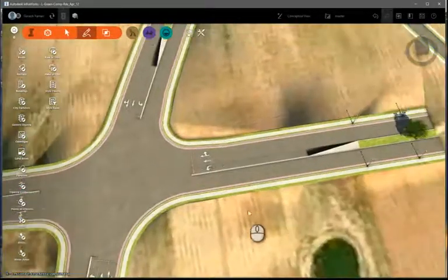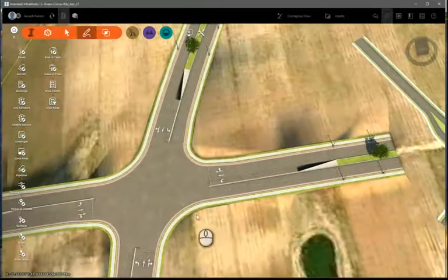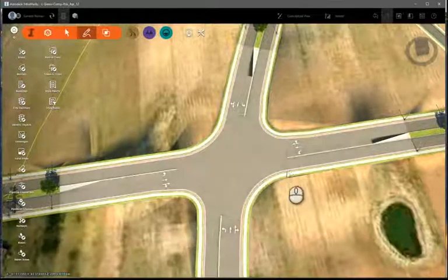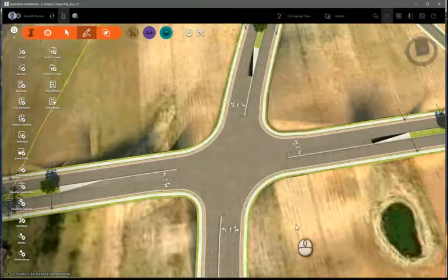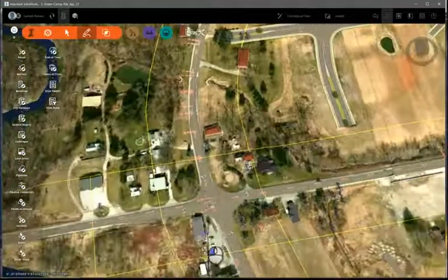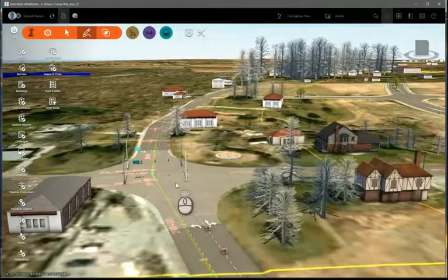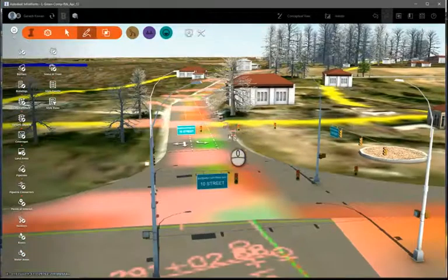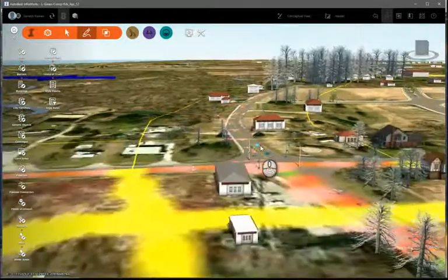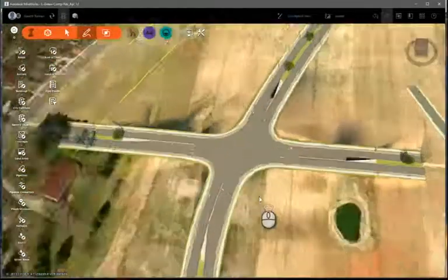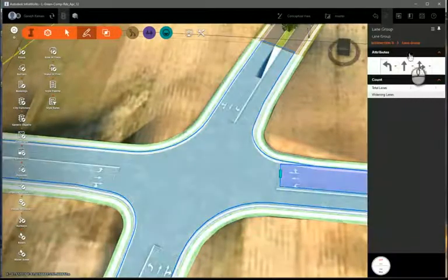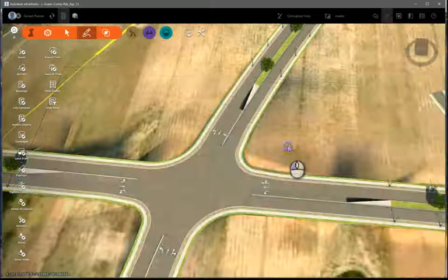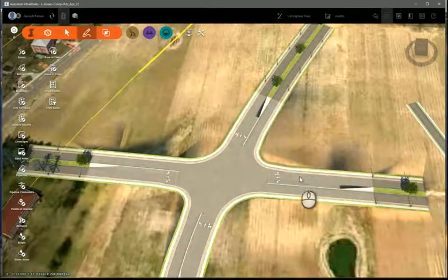Now, in reality, when there is snow on the road, these lane markings will not be visible. However, the matching of the through lanes are required because the traffic lights are going to show what the lane configuration is. For example, here, the traffic lights are going to have signs that show what the through lanes and what the lane configuration is, basically something that looks like this at the intersection in each direction. So this will now match what is exactly on the field and will not create conflict for through traffic.